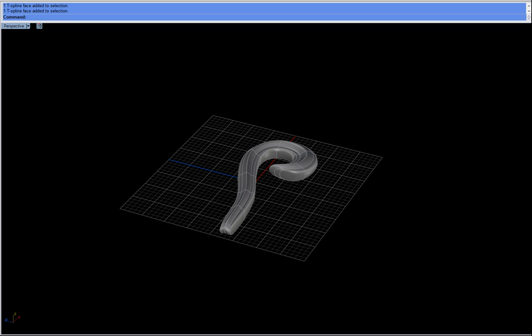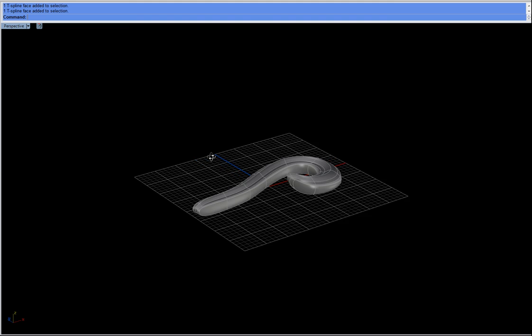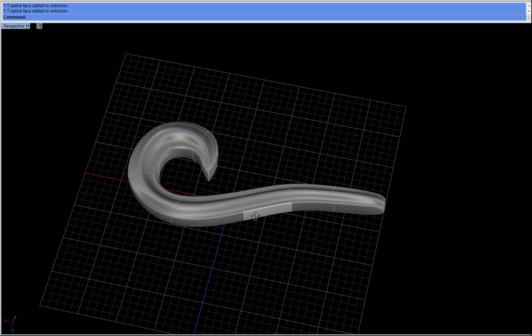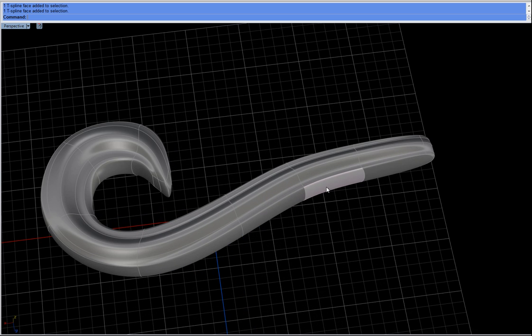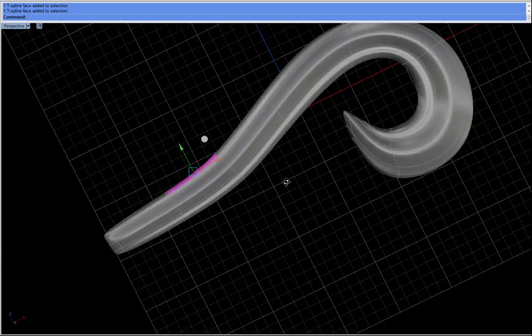The little offshoots that we had in this image, like these here, if you had this planned out, like if you'd done a sketch or something, you could definitely use this as part of your pen face. So before you did your extrude or your thicken, you could have this laid out, so you would just extrude another set of faces off of your original. But if it's an afterthought, you can still do it. It's just a little more challenging if you don't already have geometry where you need it.